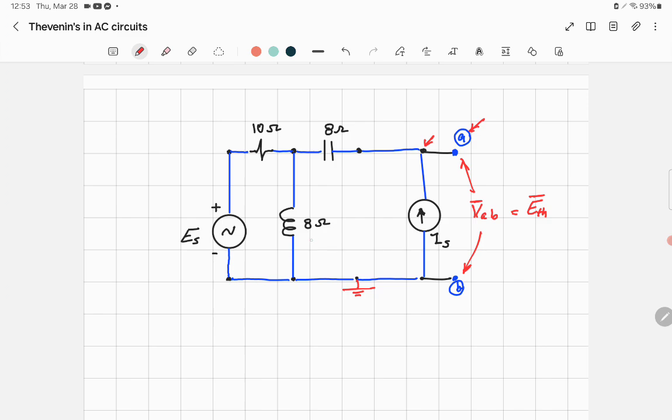In this circuit, you observe that you have two loops. So you think, can I use the mesh current method or the node voltage method? Both can be applied, and both can help you find the solution. Try always to find the easiest. Well, I have mixed: a voltage source and a current source. You can try it at home by converting the current source to a voltage source and using mesh. But here I'm going to use the node voltage method.